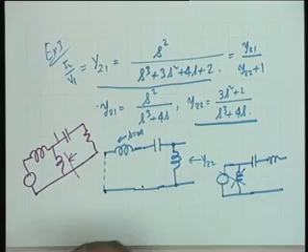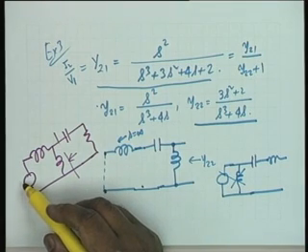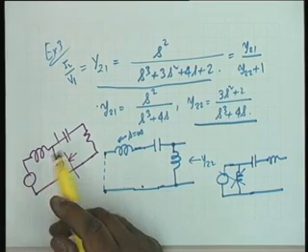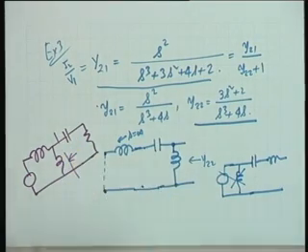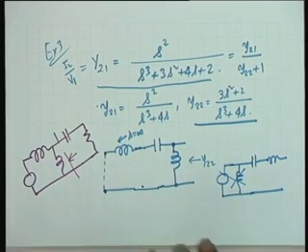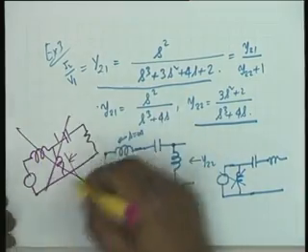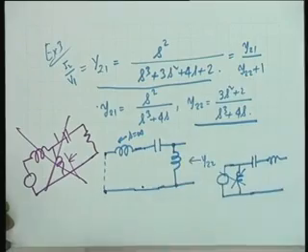Because if you look here, the Thevenin equivalent is simply a constant multiplied by this V1 in series with an inductance, and therefore one transmission zero at infinity and one at the origin. That's all. The third one is not realized. You have to be very careful in this. So this is not admissible. All that you have to do now is to realize this structure.